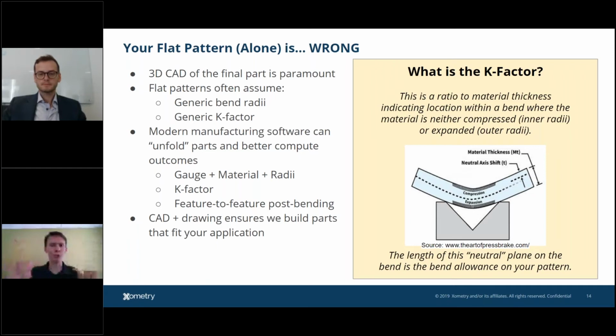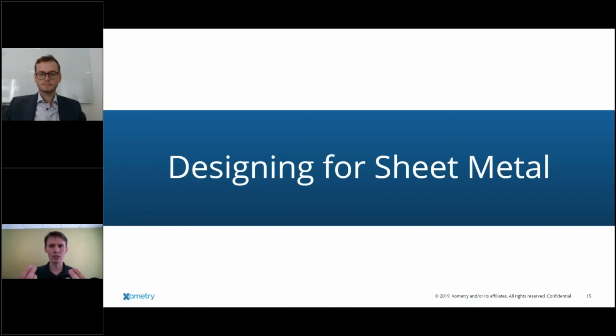So when you look at Xometry's website and you look at our general tolerance for sheet metal, you'll see 20 thou. But just understand that 20 thou is because the assumption there is in a bend condition. Because you're adding at least 1 or 2 bends, you're adding that extra tolerance, extra wiggle into your design. If you have 2 holes on those features, again, they have more of a machine-like tolerance because I'm using something with a linear XY that's creating that feature. So this is on our website, but I do want to point out that general tolerances tend to have these layers to them, whether it's a forming or bending tolerance, bend to hole, linear dimensions, diameters, all those things come into mind, even angularity, which is like that angle of bend there.